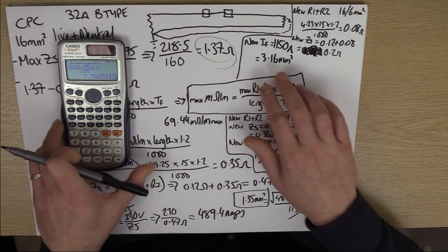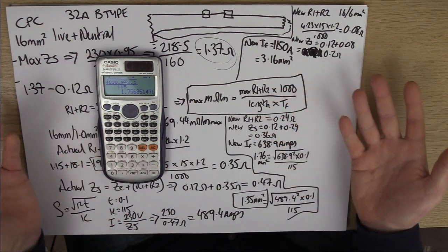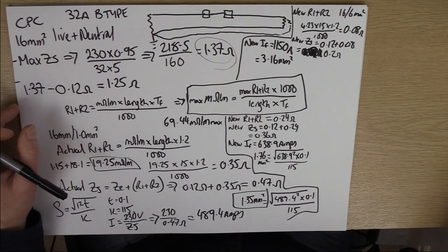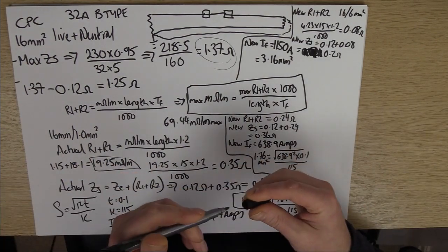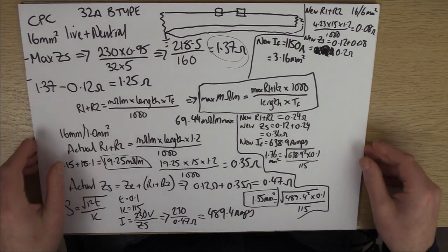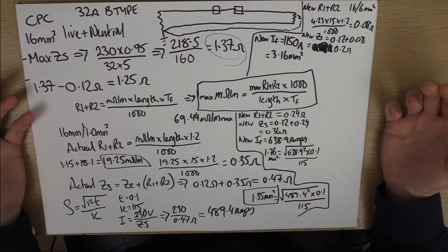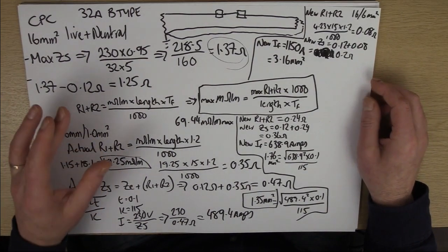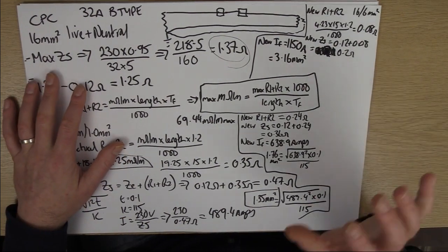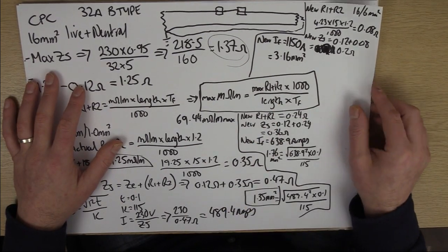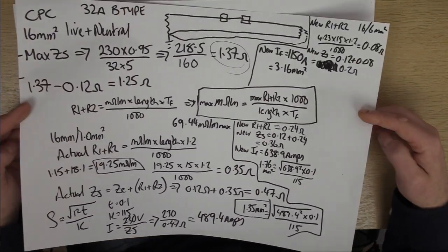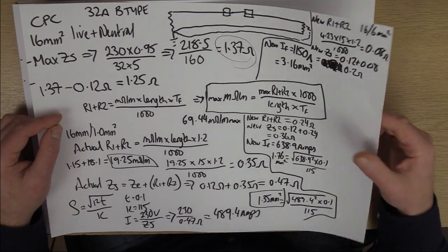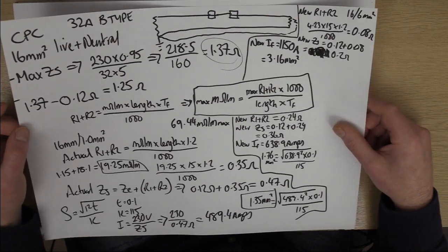And now it works. Now you probably could go down to a 4mm, but to be honest, I think I'll be tired by that point. I'll just go, oh, 6 will do. And at the end of the day, as long as this all complies, then the circuit should work. That's what we're after. So as always, two checks for CPC. It's your Zs, but it's also its adiabatic. Quite pleased with that example actually. Now let's leave it there, eh? I'll see you next time.